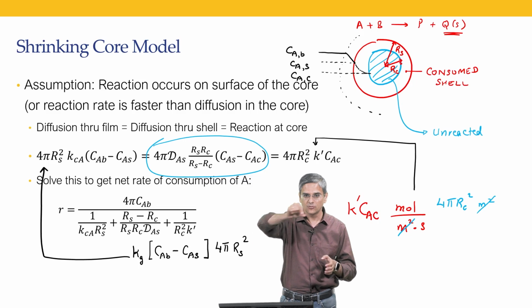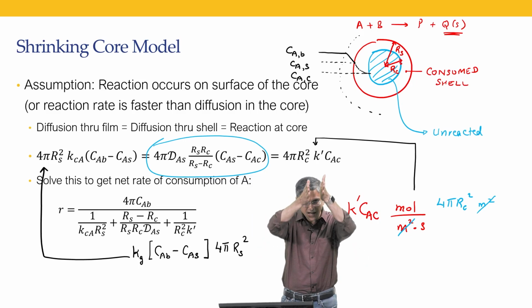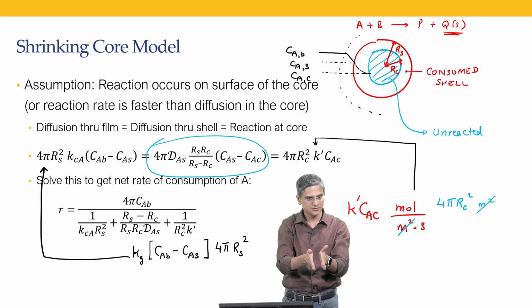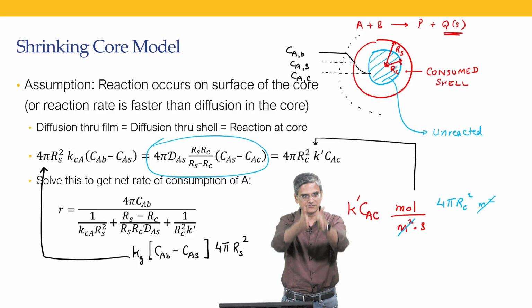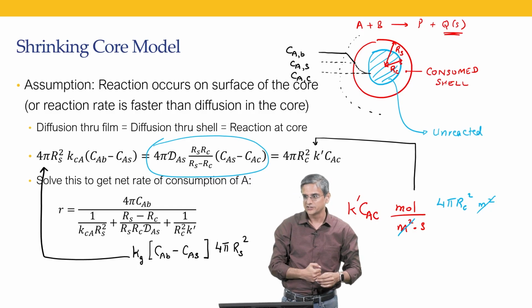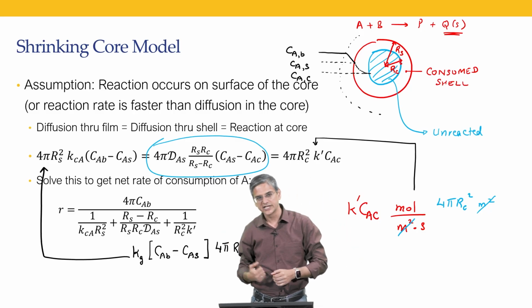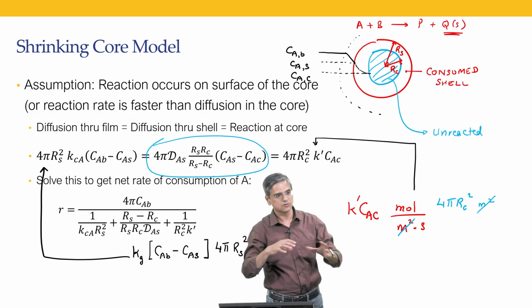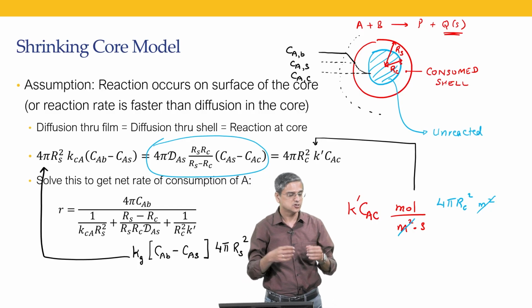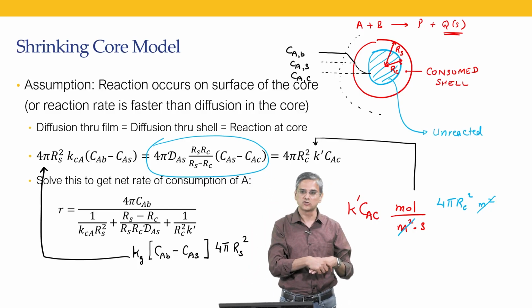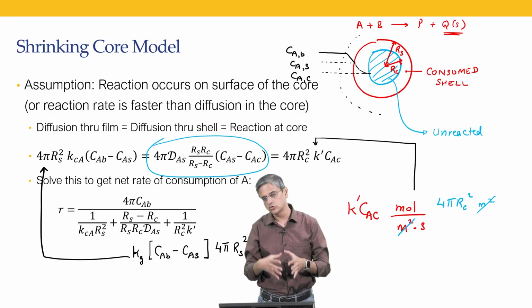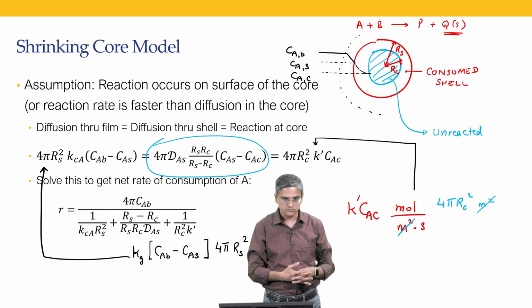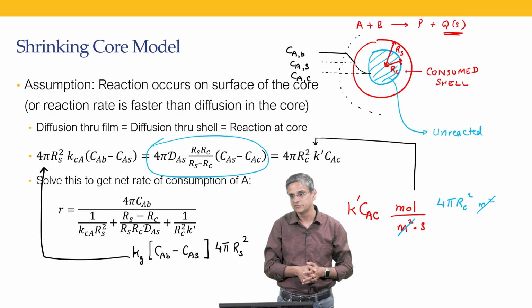When you do that, you want to etch those cavities with walls as vertical as possible, but because of diffusional resistances, the deposit does not form as a vertical wall, but as a non-vertical wall. That was what was limiting feature sizes in microelectronics 10 years back. Today we have much more precise control over how we do this deposition and etching, which allows us to go to smaller and smaller feature sizes. That has been the role of chemical engineers in microelectronics.